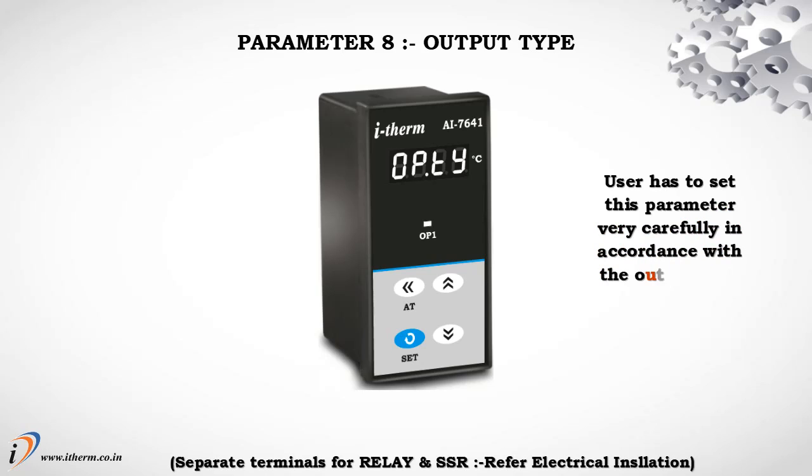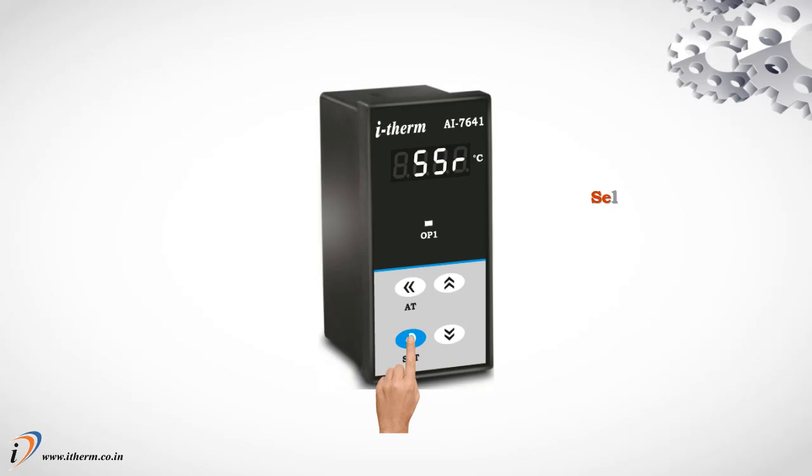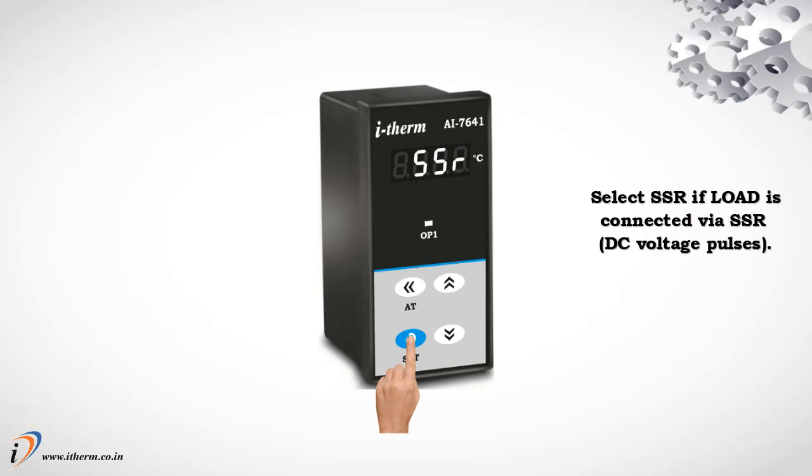Parameter 8, output type. User has to set this parameter very carefully in accordance with the output used. Select relay if the load is connected via contactor. Select SSR if the load is connected via SSR.